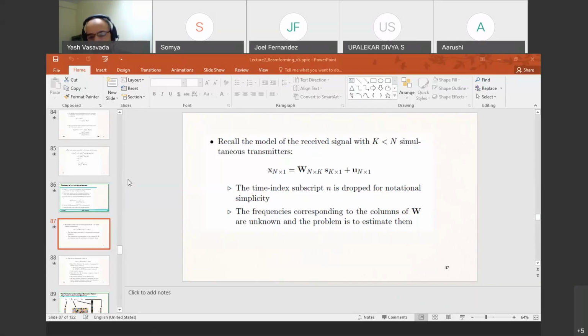Basically, we have a frequency spectrum that we are interested in evaluating, and we want to know what parts of this frequency spectrum are occupied and what are unoccupied. And it is those unoccupied portions which we probably want to use in an opportunistic manner. This is a very pertinent problem in the context of 5G and the next generation systems, especially because, as you know, there will be a very massive wireless sensor network that is being envisioned in context of 5G systems.